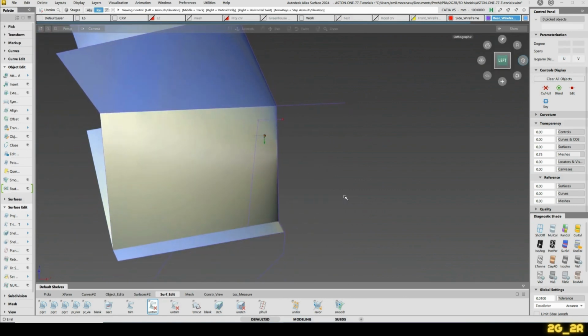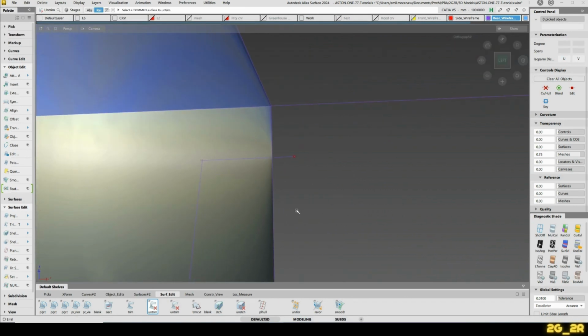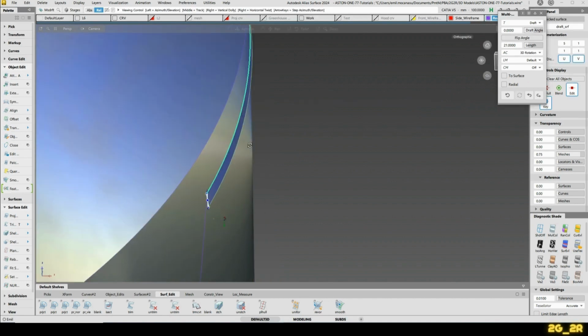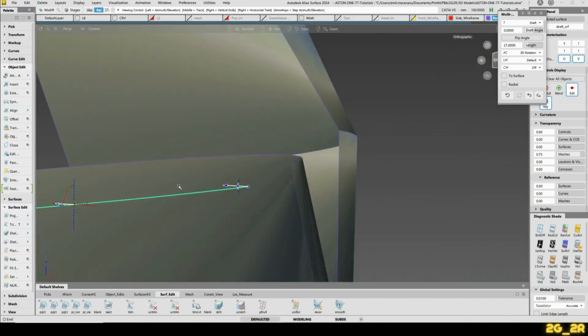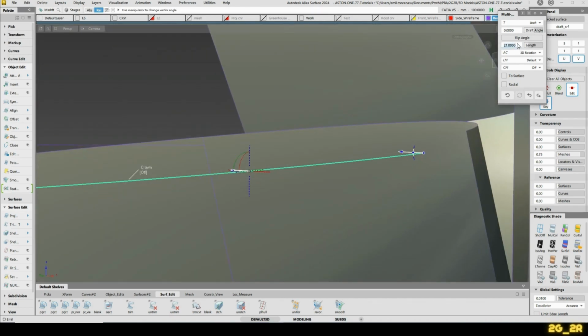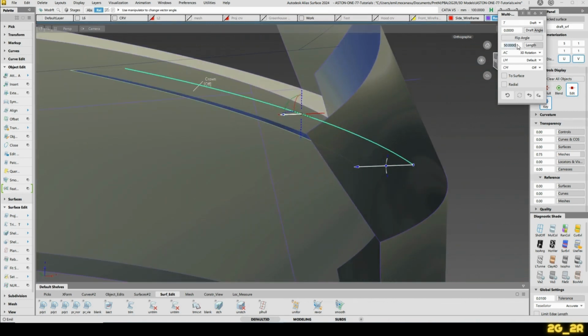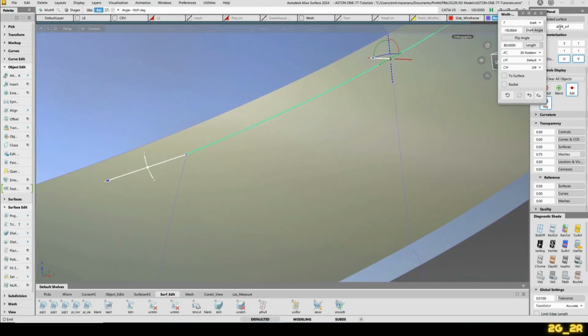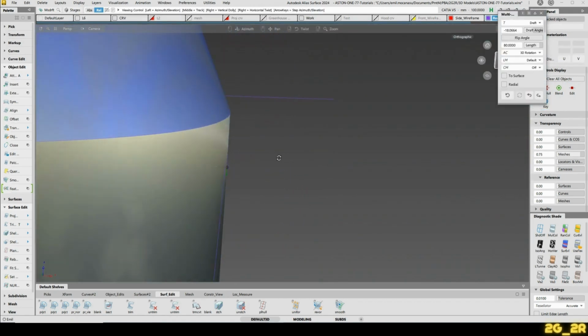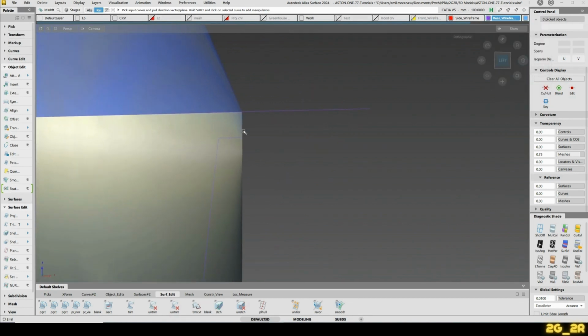And the simplest way of banging in some surfaces in here is basically doing some drafts. So, do a draft in the X direction. Make sure it pierces through the other surface. There we go. Be more generous. Overbuild is the way to do this. This way we also have some angle on it.